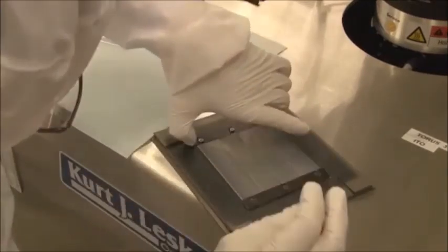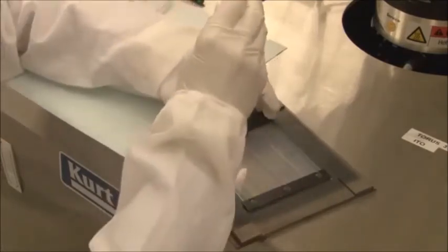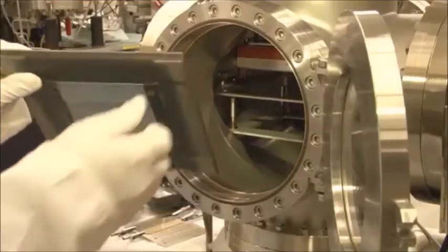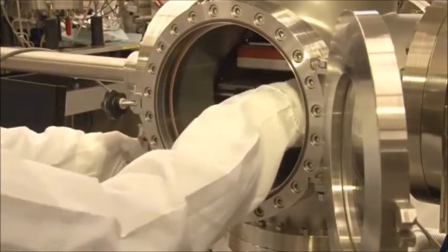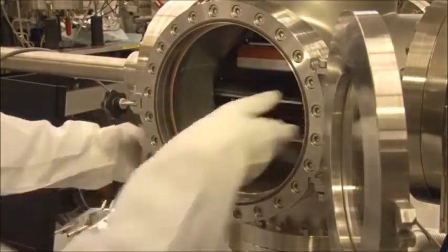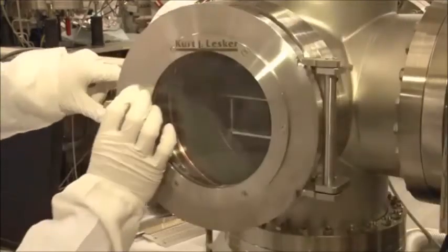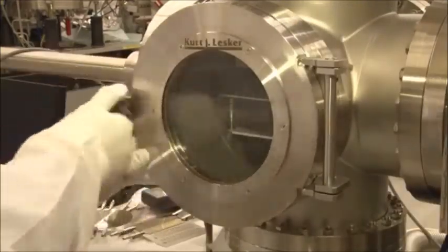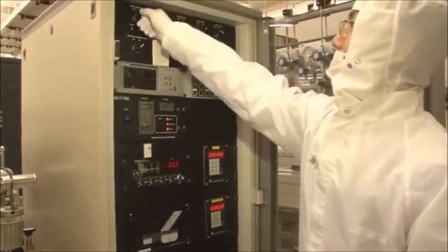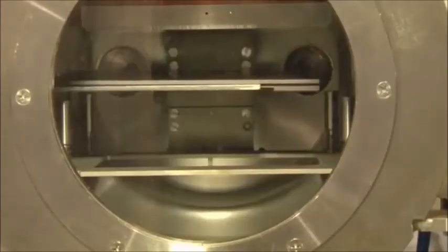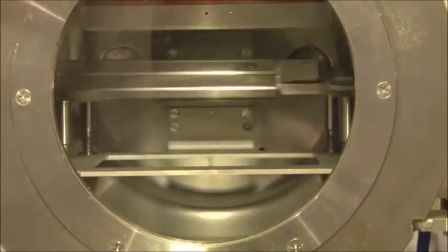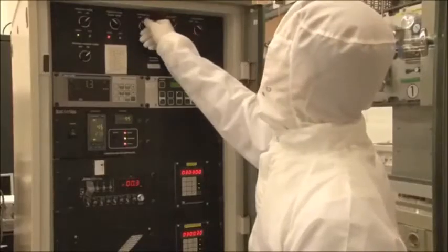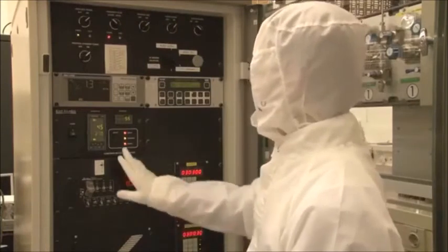In this movie, we deposit a thin zinc oxide layer on top of the Asahi substrate to protect the tin oxide from the next processing steps. The substrate is mounted on a sample holder and put into a load lock. A load lock is a chamber in which the substrate is brought under low pressure before it's moved into the processing chamber. This avoids the processing chamber being contaminated with various unwelcome atoms and molecules present in ambient air.